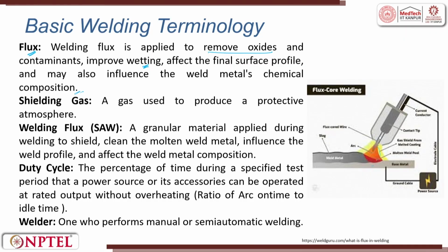That is called wetting. Say when you give a butter coat on top of a tawa, that is to make sure the wetting of the surface is improved. So, flux improves wetting, which affects the final surface profile. It also influences the metal composition.